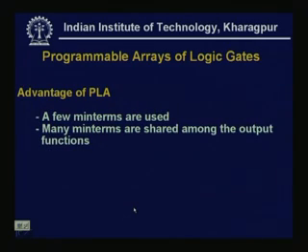Now, the advantage of PLA. We have already seen that both the AND plane and the OR plane can be programmed, and only a few min terms are used, and many min terms are shared among the output functions.